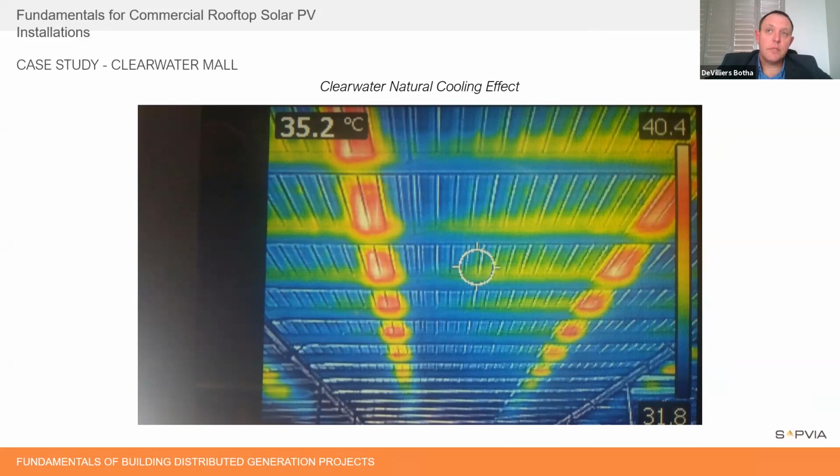With that also comes the opportunity that your roof will require less maintenance in the long term because the sun doesn't burn it anymore. However, before you start, make sure that the roof is properly painted and covered so that you don't, after 2 years, realize, oh no, there's an old problem that wasn't fixed before we fitted the PV, and you then have to remove the PV to fix that also. Just an important note there.